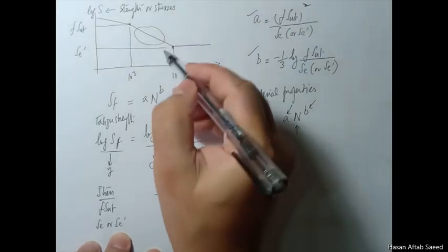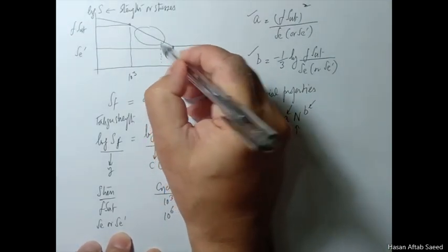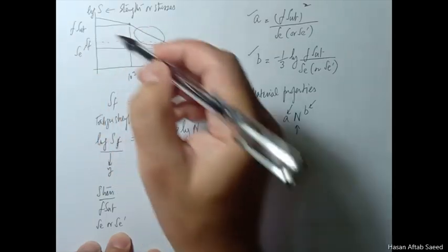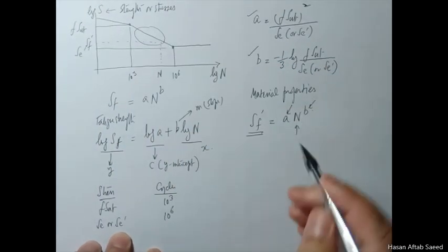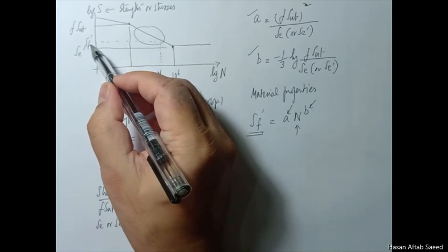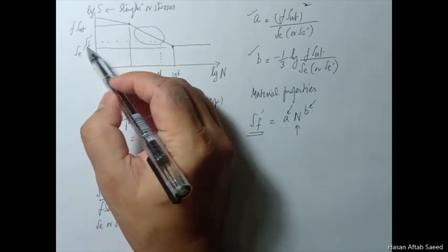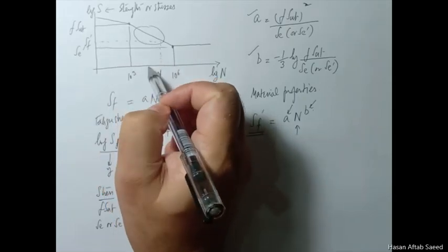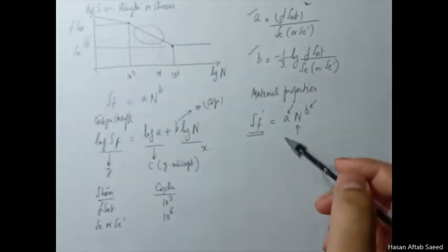This will tell you that for a certain n, this is the value, and we should write it like this because we're still in the experimental domain as yet. This much load, you cannot go beyond this load for the number of cycles to be. If you go beyond this, then the number of cycles will decrease, obviously. So this is